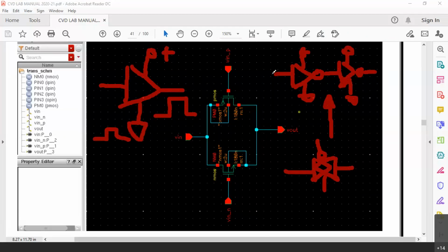As soon as the input signal is there, either a PMOS will turn on or an NMOS will turn on. When the PMOS is turning on, it is taking power from the power supply, and that power is transferred to the output. So for the buffer, the current and the voltage come from the power supply, not from the input. So basically, a buffer is what? A weak signal is made into a stronger signal, both in terms of voltage as well as current.